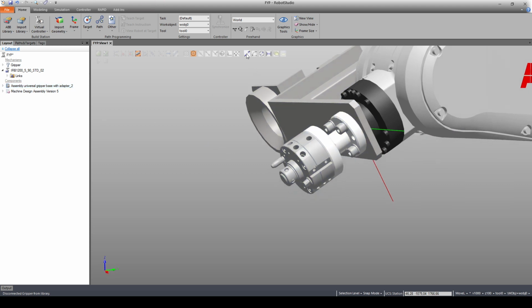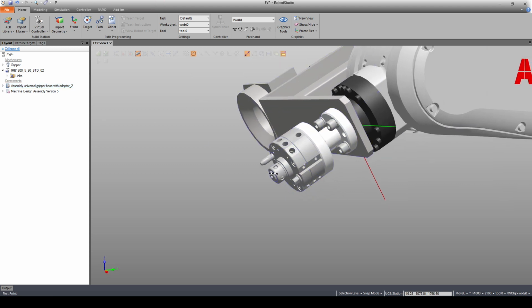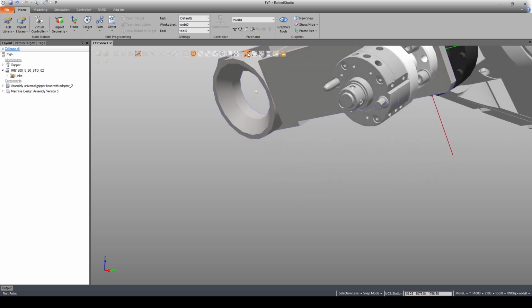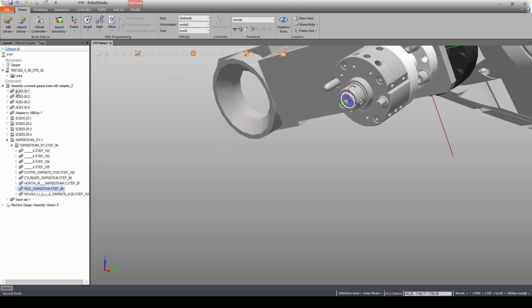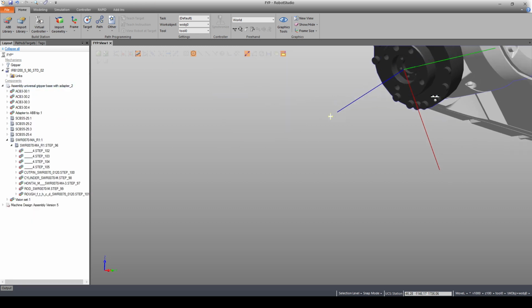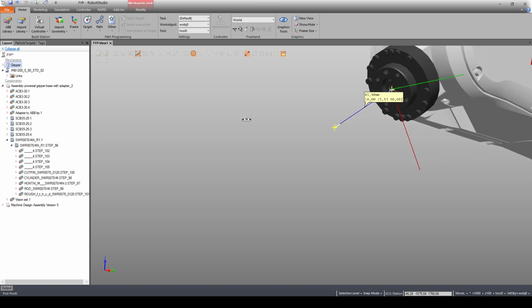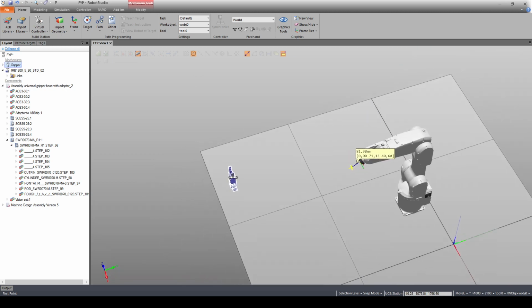So the first thing I do now is to find what this offset is, and I use this measuring tool and this center finder of circles thing. Click here, make it invisible, and then click there, and we have a value of 81.9 millimeters. Good thing to note this down in Notepad or something. Next thing I do, he has already created a gripper, so it's over here.